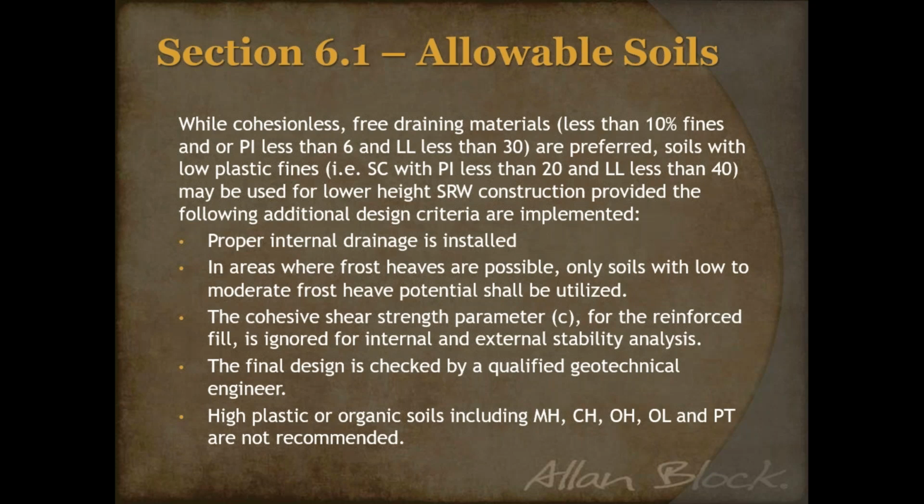We do see it in global stability calculations, but even then, you'll see it in best practices as we recommend using only a certain percentage of the tested value. We say no more than even 10%. We know that's conservative, but we also have seen far too often where walls are banking on that cohesion to help keep that soil stable, and then all of a sudden a little water is introduced and that value is no longer there.